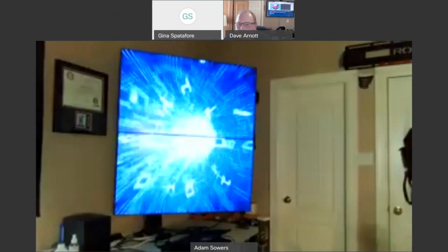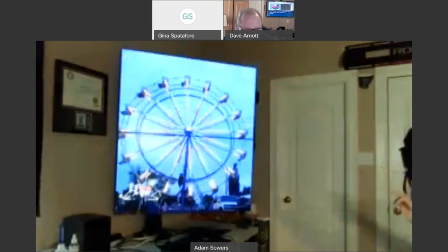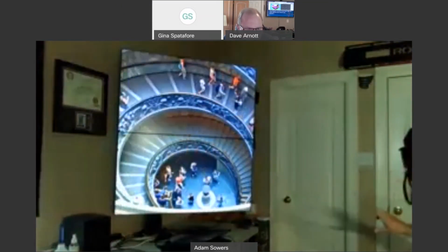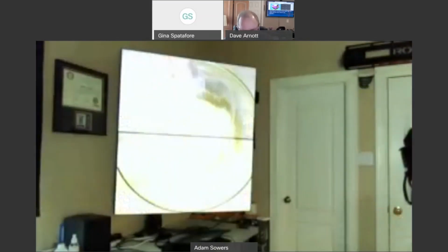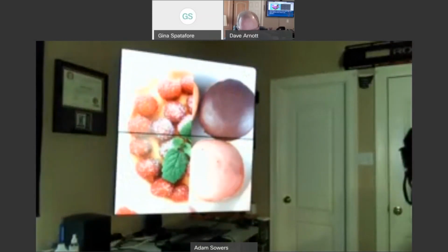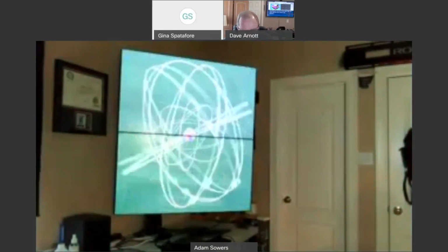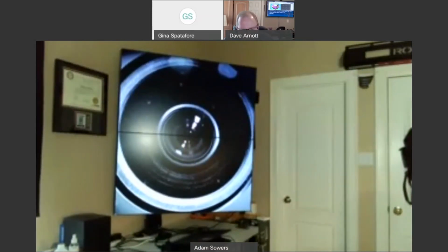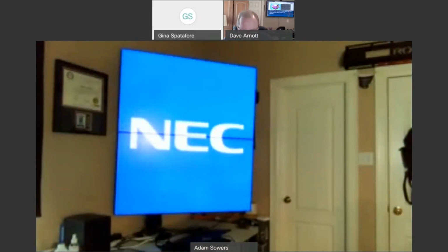So what Tile Matrix thinks it has is display number 1, or the top display, is position 1, and display number 2 is position 3. So it actually thinks there are 2 other displays to the right-hand side of my wall. And where this really becomes important is with a feature we've covered called tile cut. The content that you're currently seeing is standard 16:9 aspect ratio content. And as we all know, or if we don't know, what typically would happen with this is you would only see a portion of this content. But what we're able to do with tile cut, I'll just show it here briefly.